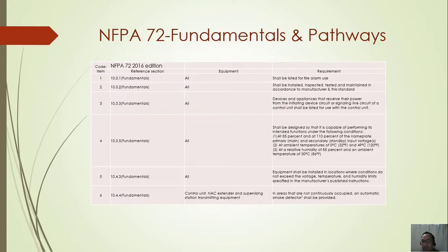That's why, guys, when we are proposing fire alarm devices in any application, you have to take care of these parameters. There should be a good supply of voltage from the facilities. If it's fluctuating below 85%, then you might face a trouble signal in the fire alarm.